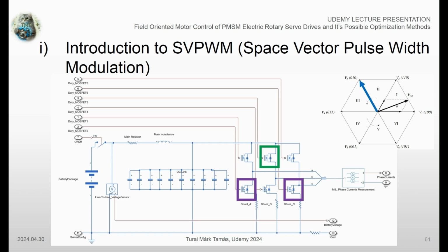So, when we are talking about either a high-side or low-side MOSFET being turned on at a given branch, it is straightforward that the other one has the opposite state. In the graphical vector representation, the 0, 1, 0 combination marks the previously mentioned state of the semiconductor devices. The V4 base vector points to the negative A-axis direction in the three-phase coordinate system.